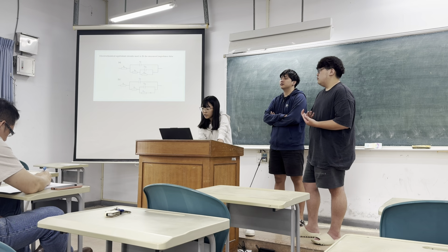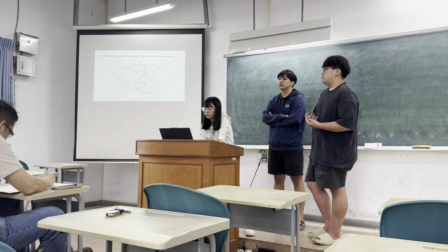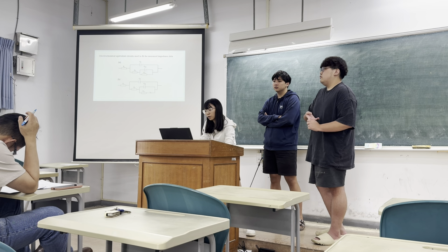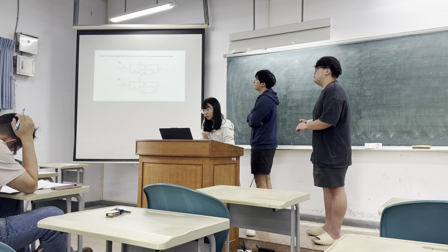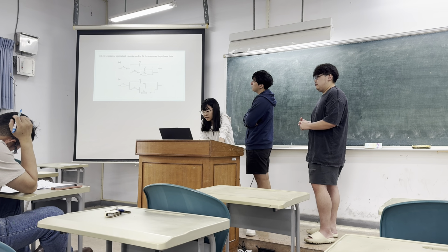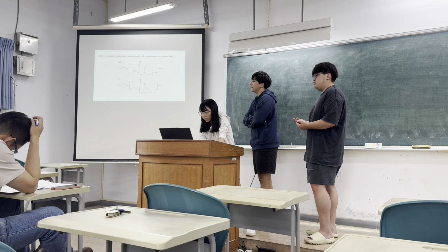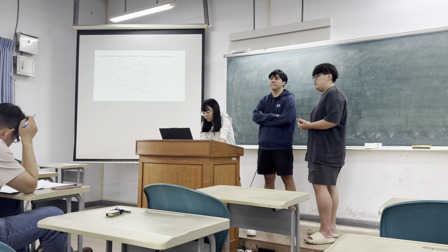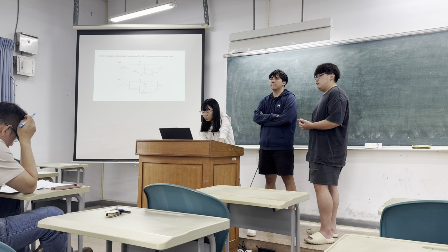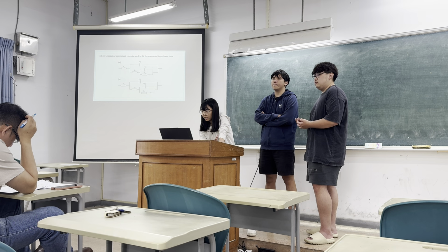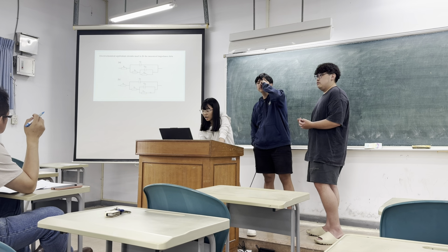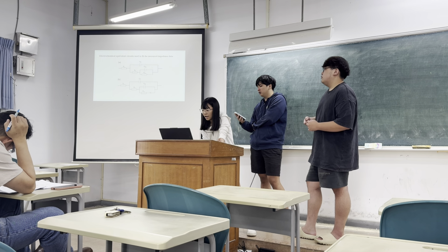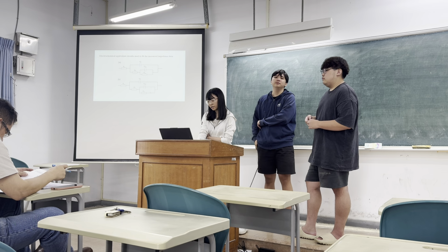And now, the equivalent circuit for the early stage or control sample. RS is the solution resistance. The first parallel loop, QF and RF, represents the capacitance and the pore resistance of the surface biofilm or passive film. The inner loop, QDL and RCT, represents the double layer capacitance and the charge transfer resistance at the metal solution interface.